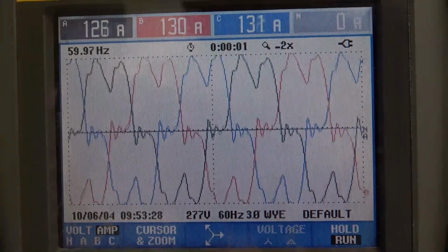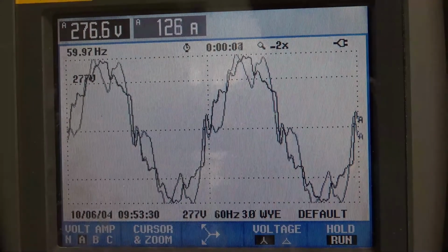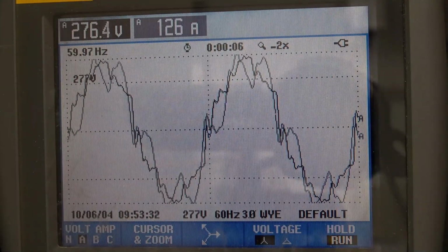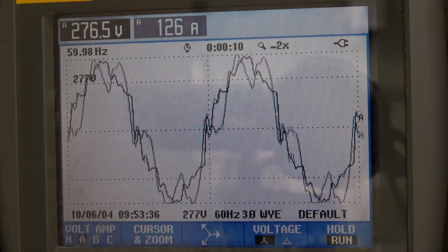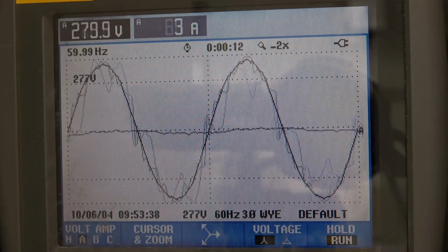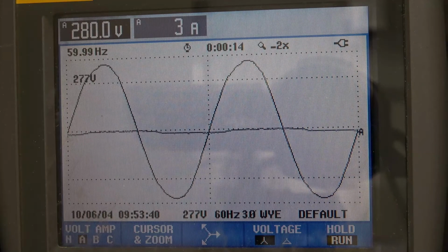But if you look at the voltage and current together now, take a look at that. We're running on the alternate source. What I'm going to do is clean up our voltage here. And how did I clean it up? I turned off the load. So again, running on the generator would not be distorted at all if I didn't have that harmonic load.